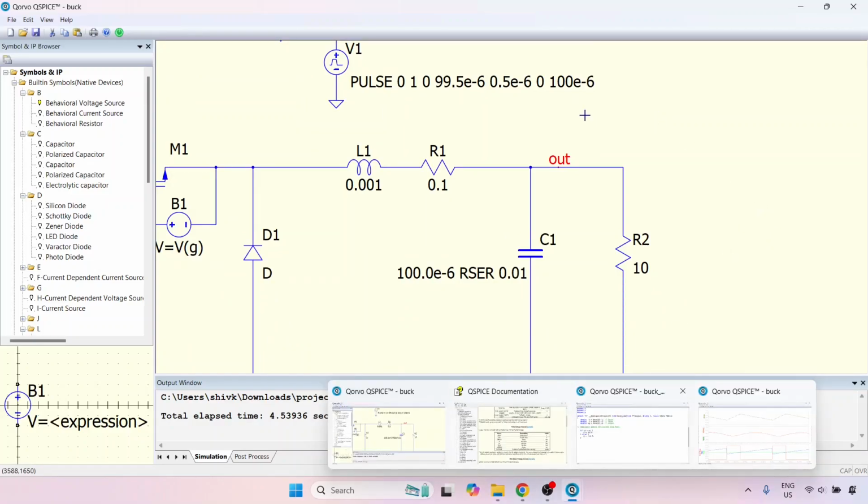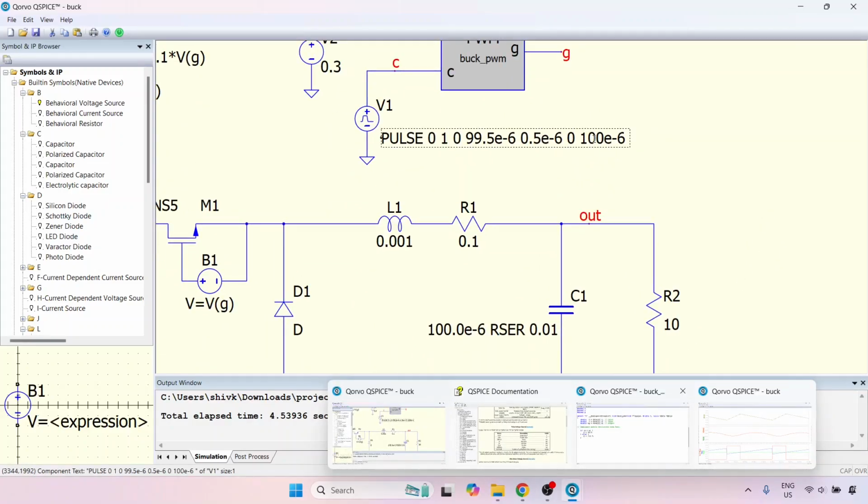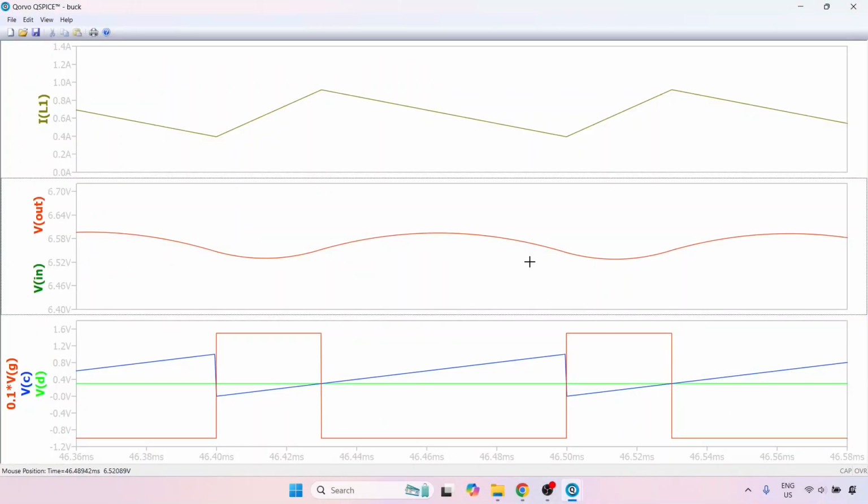And vice versa. That is, if you were to increase the switching frequency, you will see that for the same LC, or the same inductor and capacitor, you will find that your ripple decreases. So this is how we are using PWM, that is by comparing our duty ratio with a high frequency carrier waveform and generating these high frequency gating signals. We are able to filter it with much greater ease in order to produce a smooth output voltage.